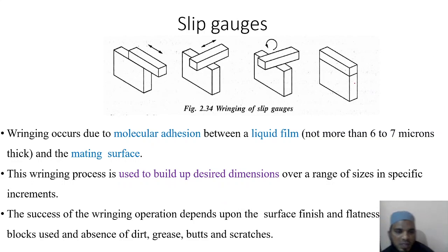Okay, the success of the wringing operation depends upon the surface finish, the flatness of the blocks used, and the absence of dirt, grease, burrs and scratches.